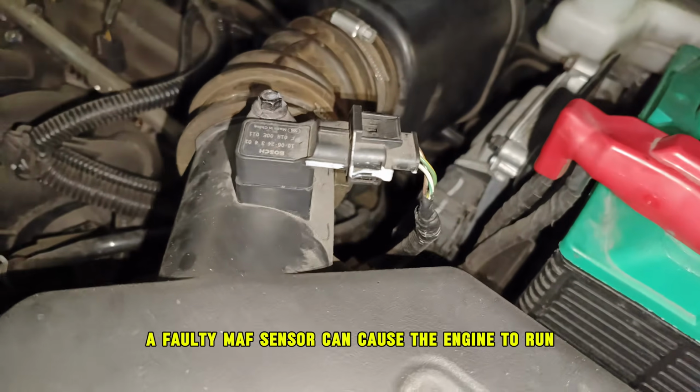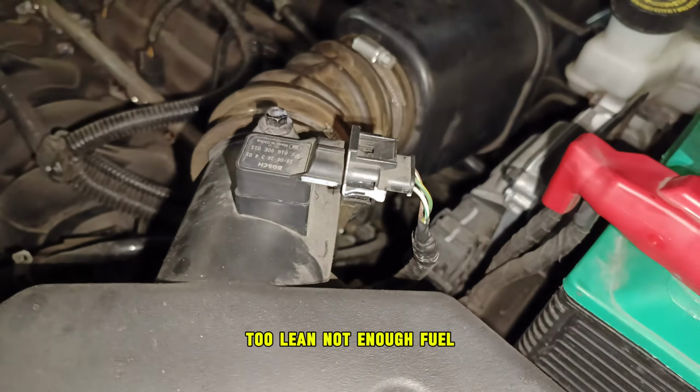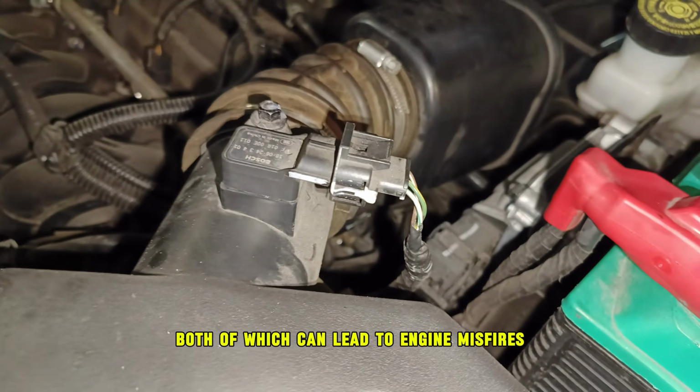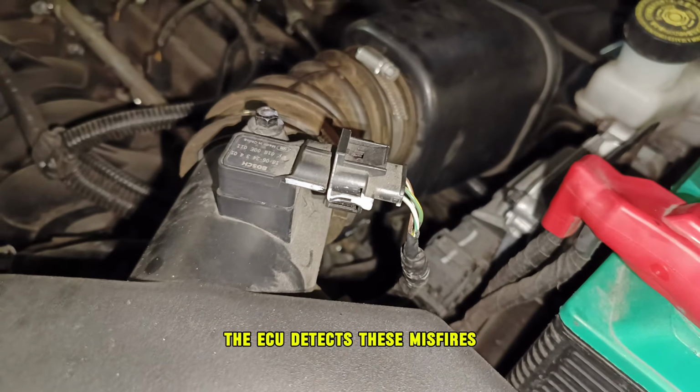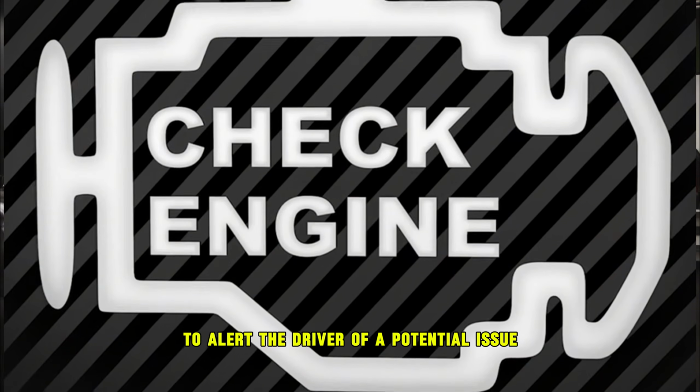A faulty MAF sensor can cause the engine to run too lean, not enough fuel, or too rich, too much fuel, both of which can lead to engine misfires. The ECU detects these misfires and triggers the check engine light to alert the driver of a potential issue.